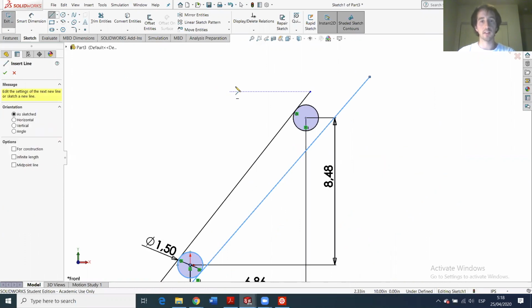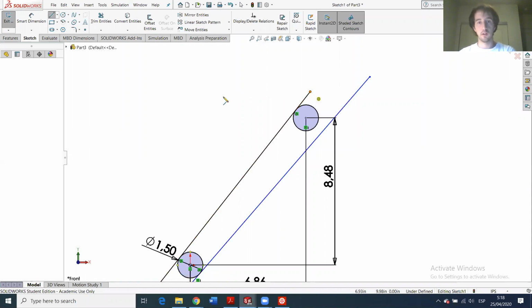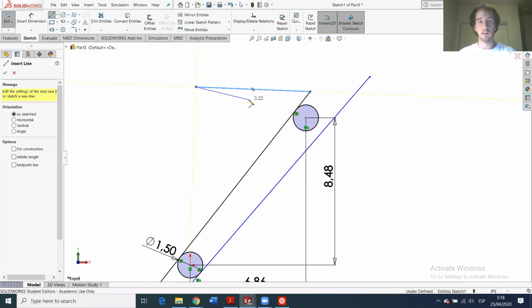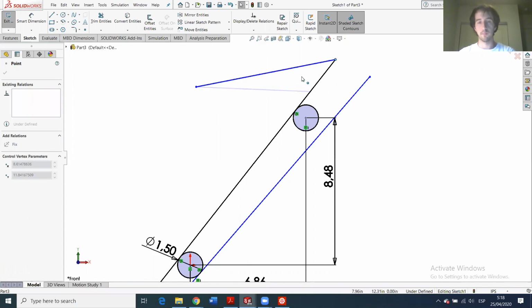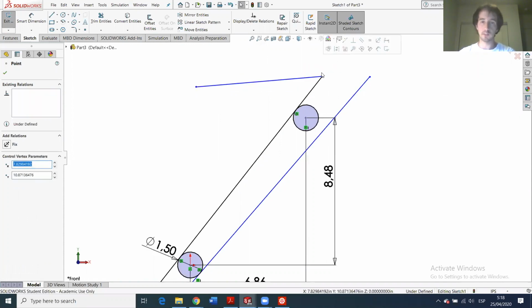And these things happen because sometimes, for instance, if I want to design a line and I start from here, sometimes you see that this dotted line appears. Then the line will be designed with a relationship. You don't have to design it. For instance, if I start from this point and I end the line here, this will understand that this point is together. So you don't have to say that this point from this line and this point from this line are coincident. If you start from this point, they will understand that it's coincident.